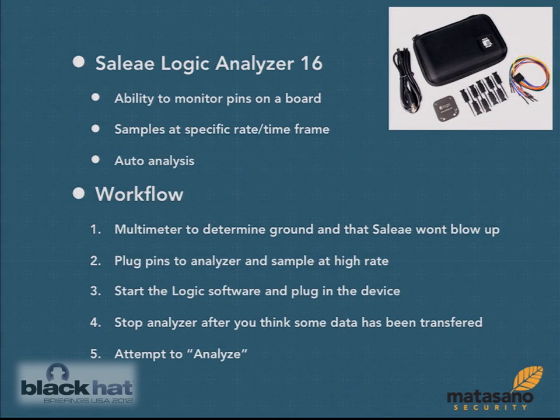And the tool that I used to actually analyze the data that was going over this is called a Saleae logic analyzer. A logic analyzer is a device that you connect to these specific hardware pins, and it will sample those pins at specific intervals in time and over a specific amount of time and tell you if it's a 1 or a 0, basically if it's a high voltage or no voltage, and then from there it can analyze that set of data and give you a text representation or a hex representation of what's actually being communicated over these pins.